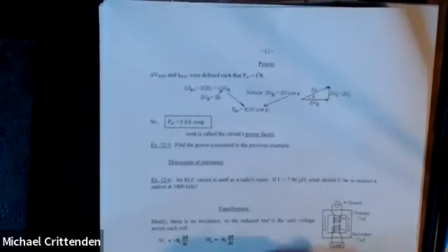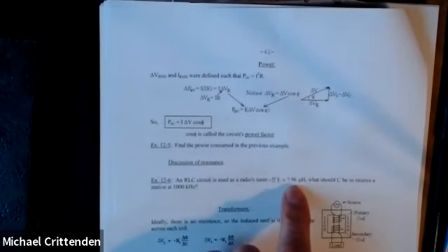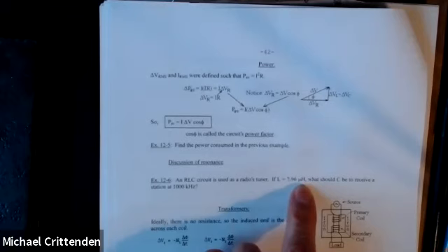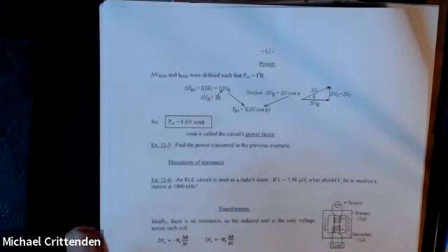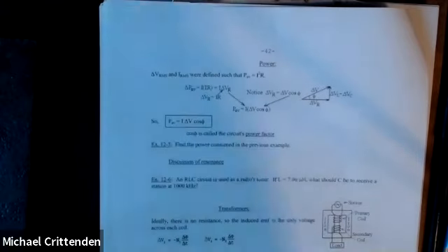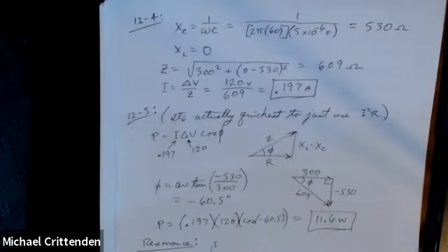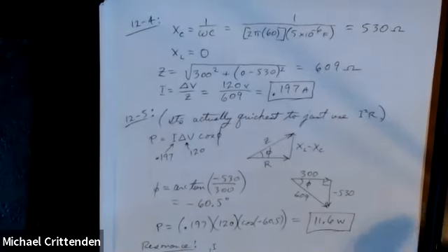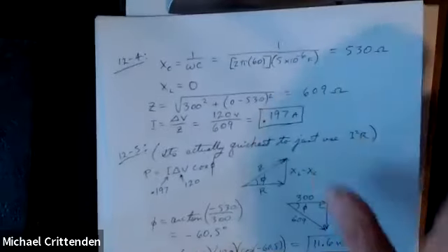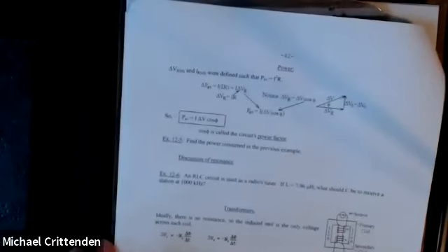So let's say that the inductance is just a little less than 8 microhenries, and the resistance doesn't have any effect on what the resonant frequency is. The resistance has an effect on how sharp the peak is. You know, is it a broad peak like this curve, or is it a sharp peak like that one? The so-called Q factor for that. If you're interested in learning more about this, you could look that up. I think it's in the textbook. If not, like everything else, it's on the internet.